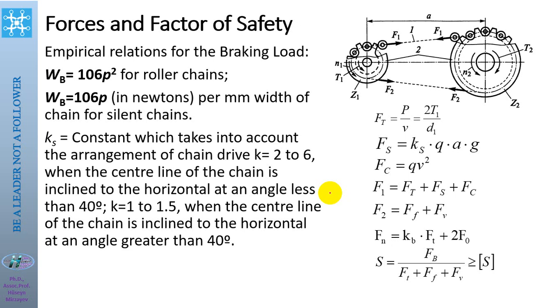Which force acts on the chains? Force acting on the sides of the chain, F1 and F2. And tangential force, transmitted force, calculated using these equations: P divided by V, velocity, tangential velocity, or 2T1 divided by D1, where T1 in this formula is torque on the driving shaft.